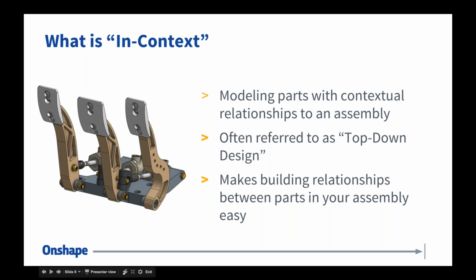Question: can you move an individual part from a Part Studio to a separate document? That's a good question. An individual part from within a Part Studio to a separate document. I don't think so. You can, of course, copy the tab, but that's everything in it. We could discuss workarounds where you could delete parts and things like that, but I would ask why. What do you want to do by separating the part from the Part Studio?